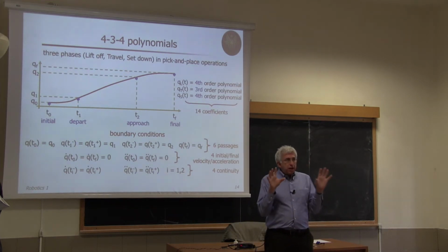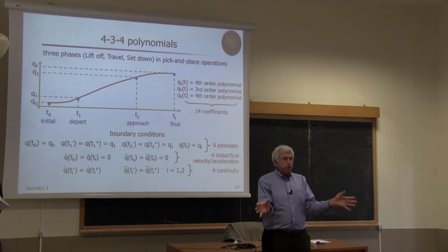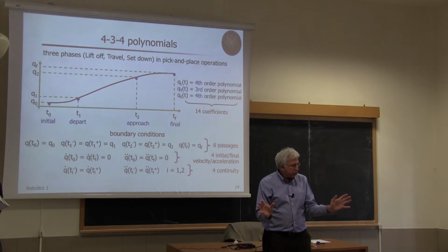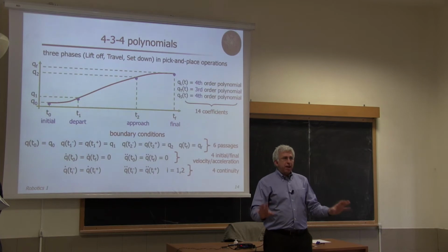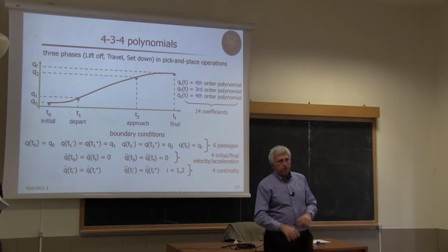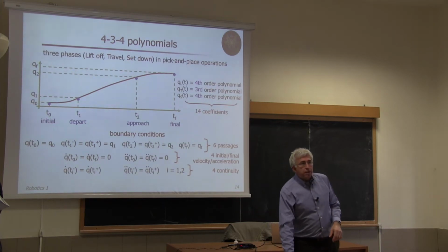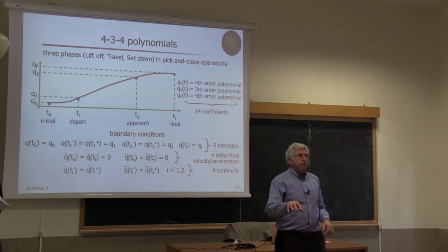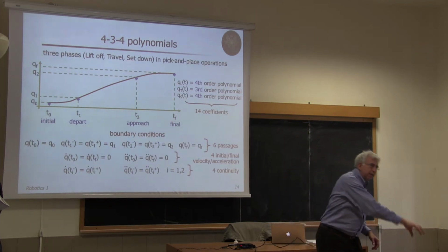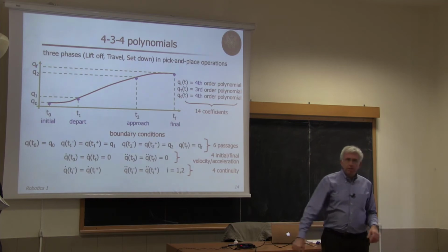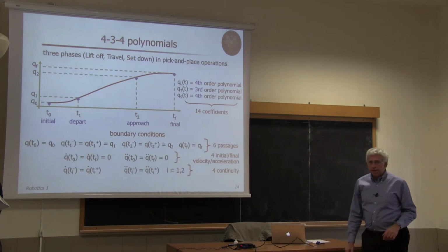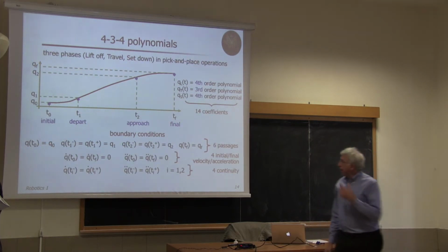So these 2 points are imposed so that the initial and final part of this trajectory do not have any wandering or overshooting. So that we really are very carefully departing from a touch condition, do whatever we do, and then approaching and touching again the environment. Okay? So this is the rationale.